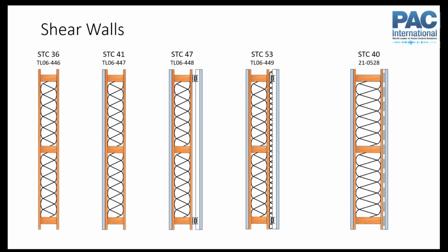So a lot of the multifamily projects I worked on, we had lots of shear panels in them, and a lot of times we would have double shear panels where there's an OSB or plywood shear panel on both sides of the wall. And for them to work effectively as shear panels, as best I understand it, they need to be tied directly to the studs, to the structure, right, to keep that structure from racking in the event of an earthquake. So that limits our abilities for acoustic isolation because typically we want to have these continuous membrane layers, usually drywall, decoupled from the studs.